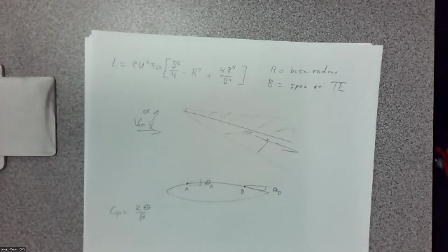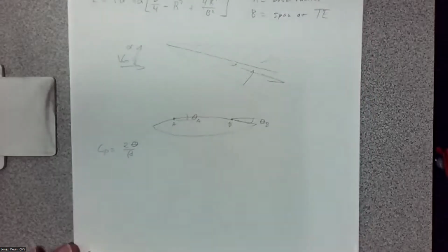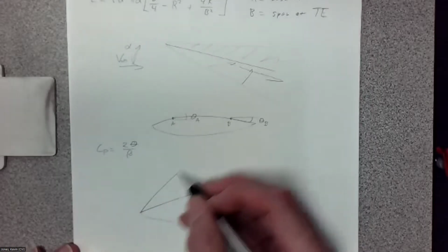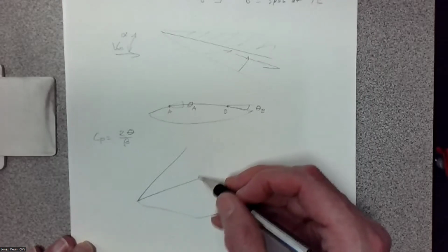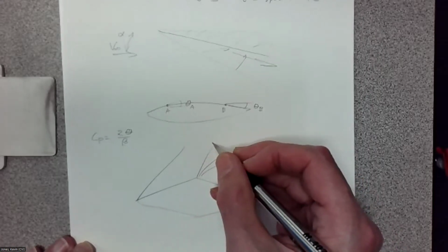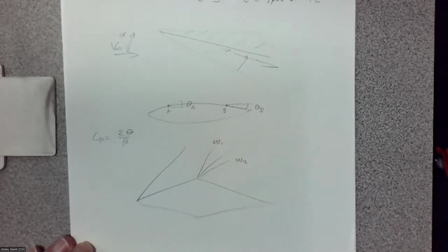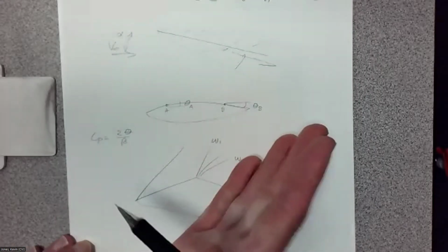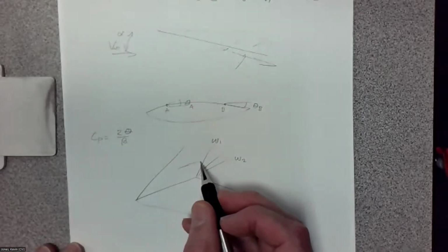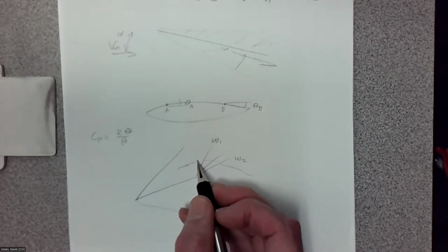For hypersonics, if you remember, I barely talked about it, but on the diamond airfoil, we've got that rooftop. So start with a shock up here, and then we have this expansion fan. And if you remember, there's a starting angle, omega 1, and then there's an omega 2, as the flow expands and the streamlines come up in the curve, staying tangent to the surface.